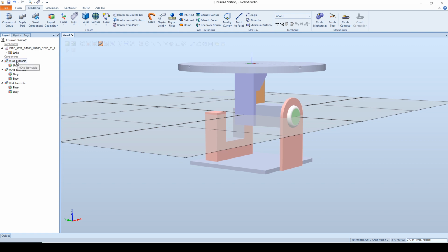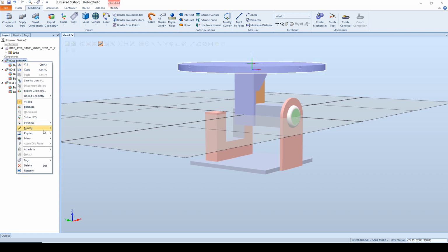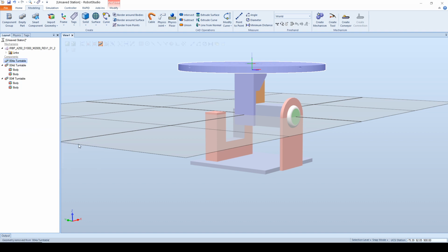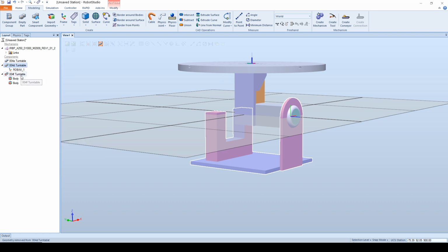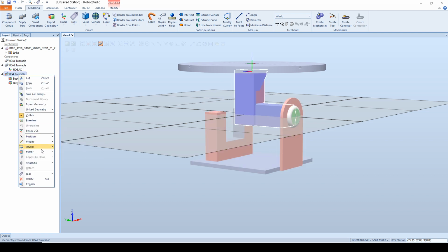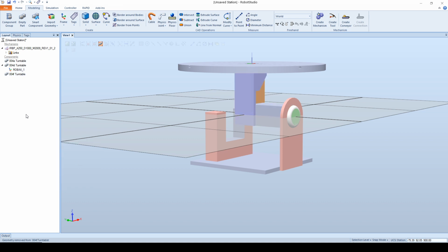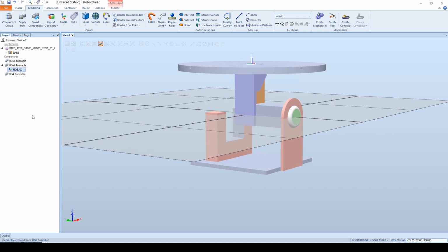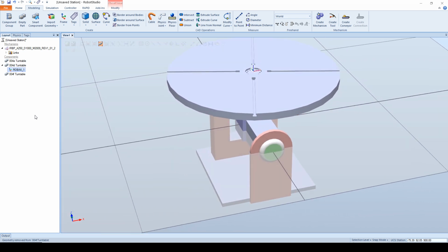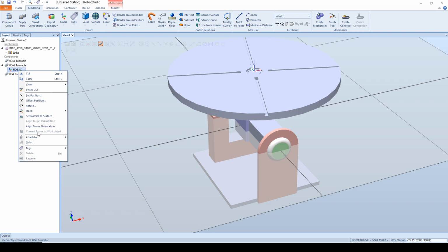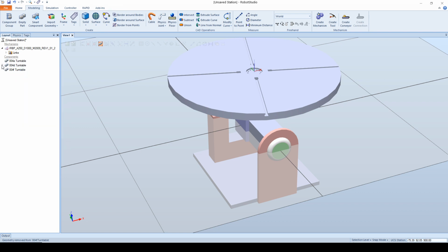So what I usually do is I go into modify and remove CAD geometry on everything, just because it's unnecessary for Robot Studio to include them in calculations. It just creates extra load. I see that they created the target here. It's not necessary. Is it not possible to remove it?